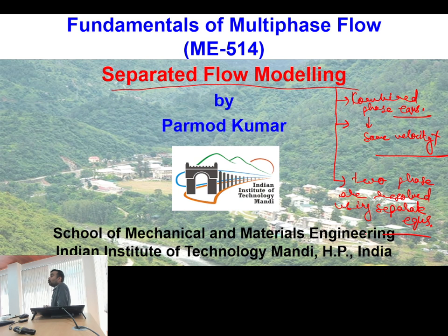So, of course, the true separated flow approach is the second one, where the two phases are actually resolved using a separate set of equations. For phase 1, there will be a separate set of continuity, momentum and energy equations. Similarly for phase 2, there will be a separate set of equations, and then of course at the boundaries, in order to interact between the phases, we will have some mass interaction terms, some momentum interaction terms, and some energy interaction terms. Okay, so that is the actual two-phase flow approach, the separated flow approach.